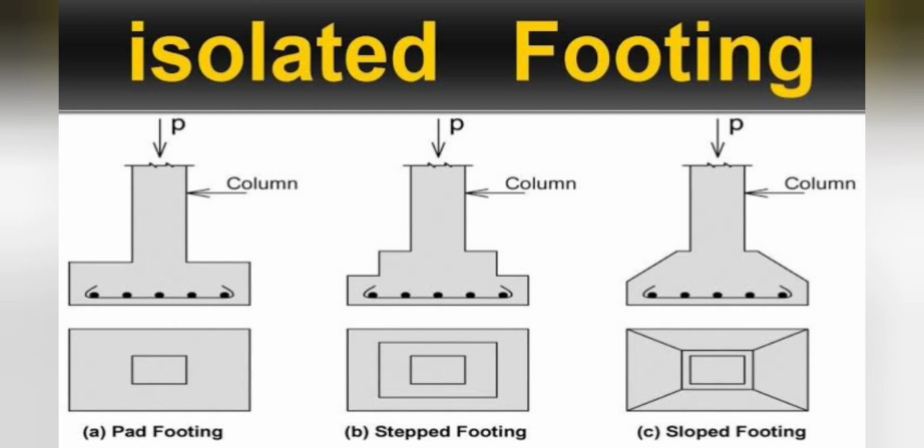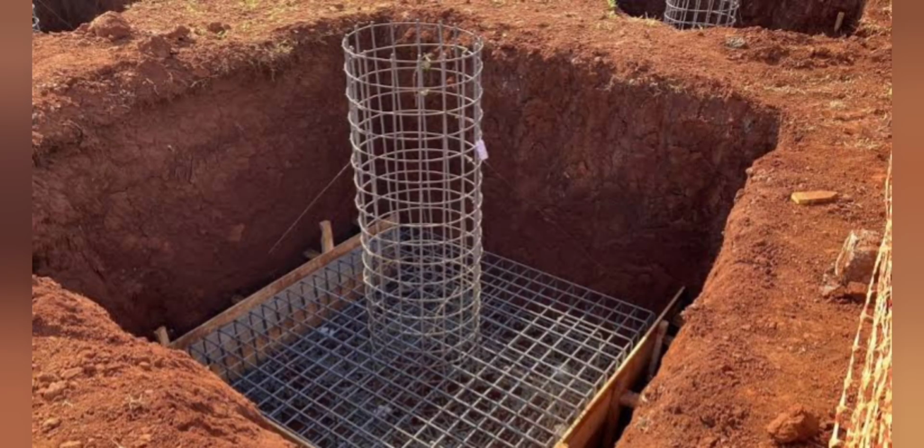Precast piles are driven and cast in situ piles are cast. They are normally provided in a group with a pile cap at the top through which the loads of the superstructure are transferred to the piles. These piles transfer load to the hard strata deep below the surface. This type of pile is called an end-bearing pile.